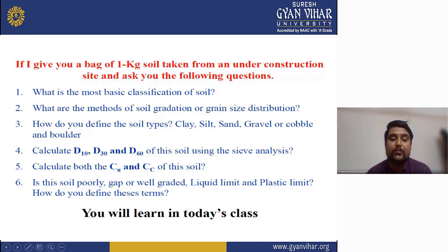What is the purpose of doing sieve analysis? This test is performed to determine the percentage of different grain sizes contained within a soil. The mechanical or sieve analysis is performed to determine the distribution of the coarser, larger particles, and the hydrometer method is used to determine the distribution of the finer particles.